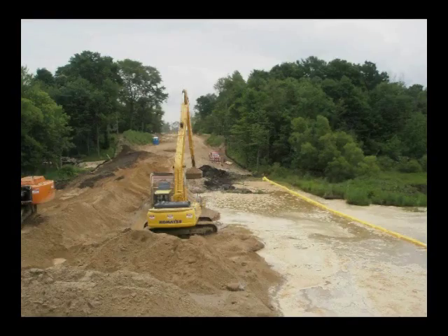The main duty of the stormwater operator is to inform the permittee of problems and corrective actions needed on site. The best way to do this is to know the site and be aware of problems so they can be corrected or, better yet, prevented. Remember, it is less expensive to prevent problems than it is to correct them.